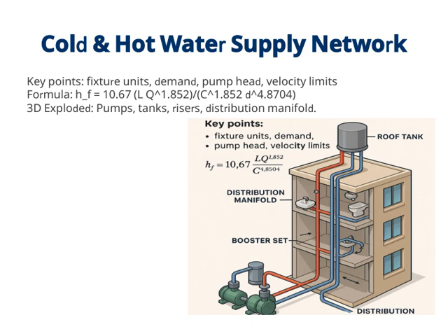Next, pump head is critical because it determines the energy needed to move water through the system. It's directly related to the height and resistance the pump must overcome. Velocity limits are also important because maintaining appropriate flow velocities helps prevent issues like noise, erosion, or pipe damage.